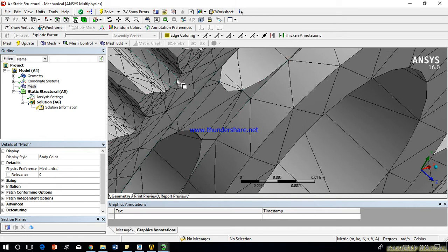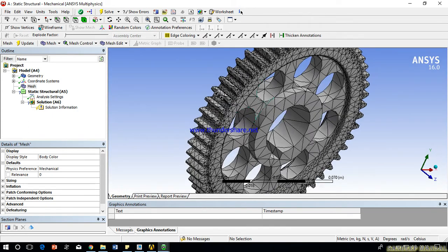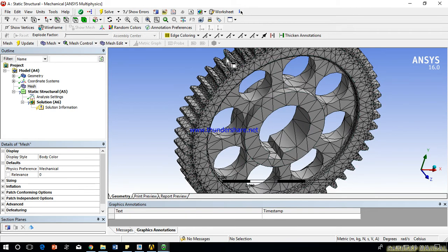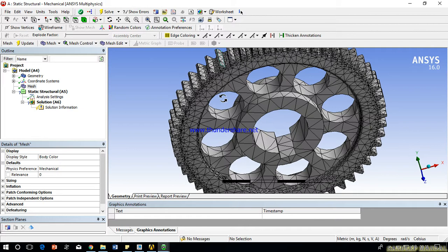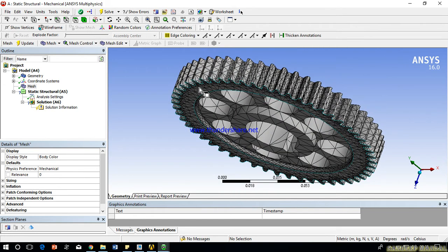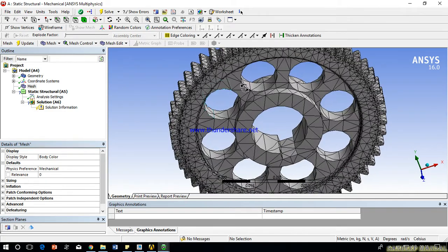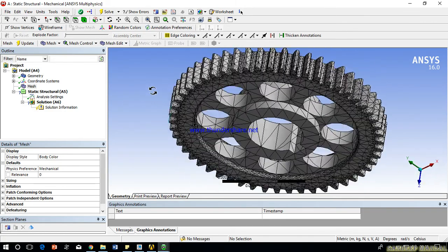stresses and strain. Some of the triangular or rectangular structures are subjected to a biaxial stress system or some to a uniaxial stress system. Mainly the outer portion is generally subjected to biaxial and generalized stress conditions, and internally the elements or shells are experiencing pure shear and concentrated forces. So it calculates for a single element in matrix form and combines them, so that our deformation value or stress value is evaluated for the whole gear.